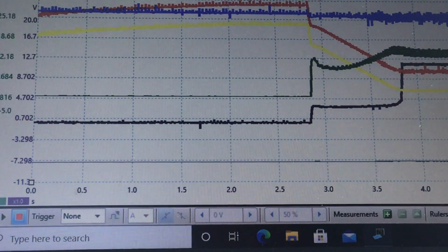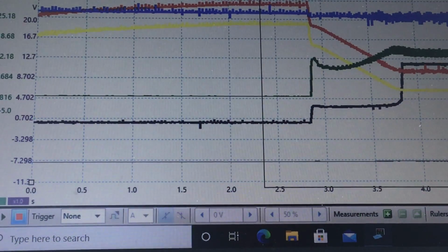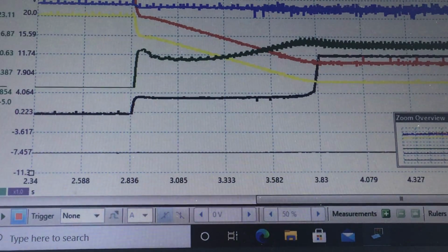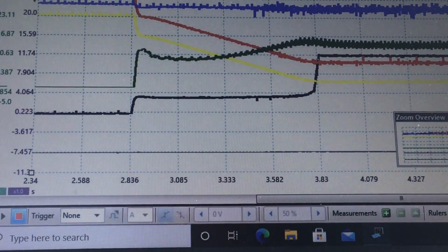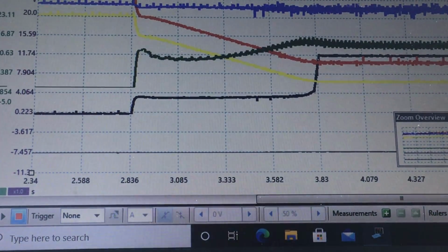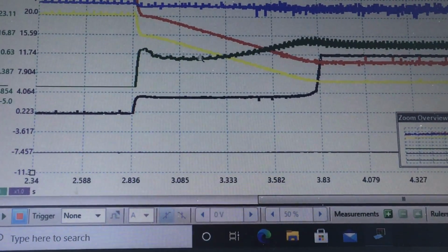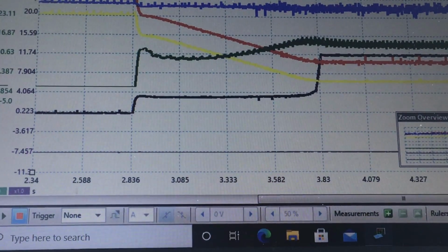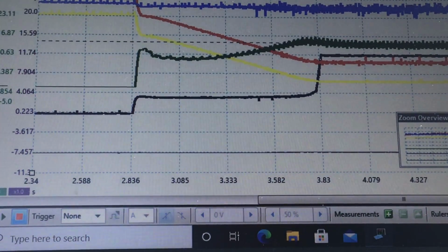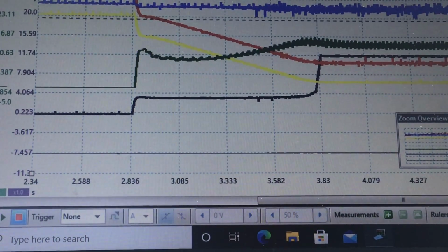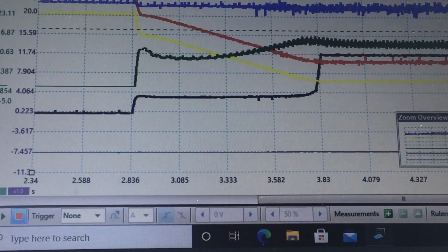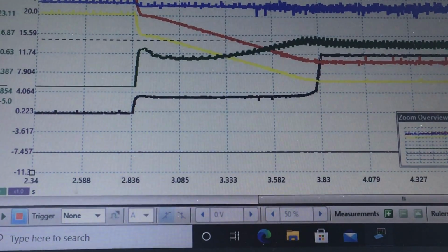Let's kind of zoom in on this puppy, and we'll analyze it and talk about it. Our feed voltage is red. Blue is the voltage going to the blower motor. As you look at your schematic, our red channel is on the ground side of the blower motor, which is sort of an intentional drop that the power transistor does. You can see it ramping down as I was turning that blower motor. I was creating more resistance each time I turned that. Actually, less resistance, because the blower motor is spinning faster.